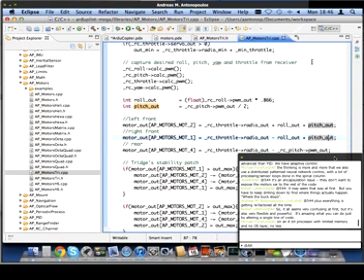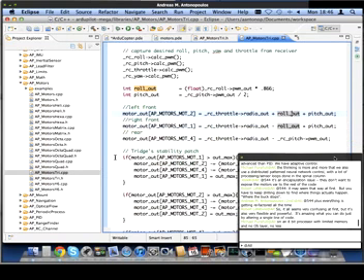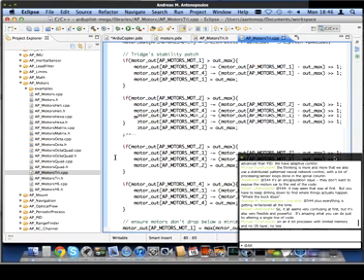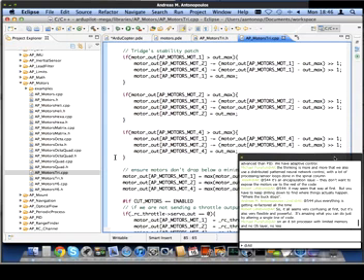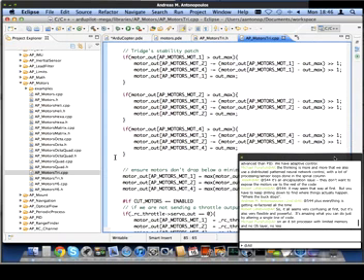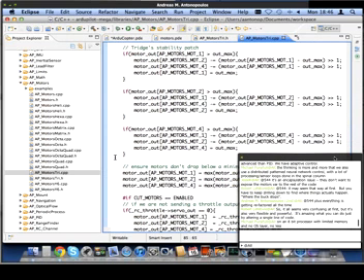So you can see we've got this motor out array here, and for motor 2, we are going to send it the RC throttle, just the basic pilot throttle. Then we're going to add to it a roll out and also a pitch out. So this is where the mixing is happening. You can look at the different frames and see how the mixing is done, but basically they're all just different combinations of the roll, pitch, and throttle provided from the PID controllers.